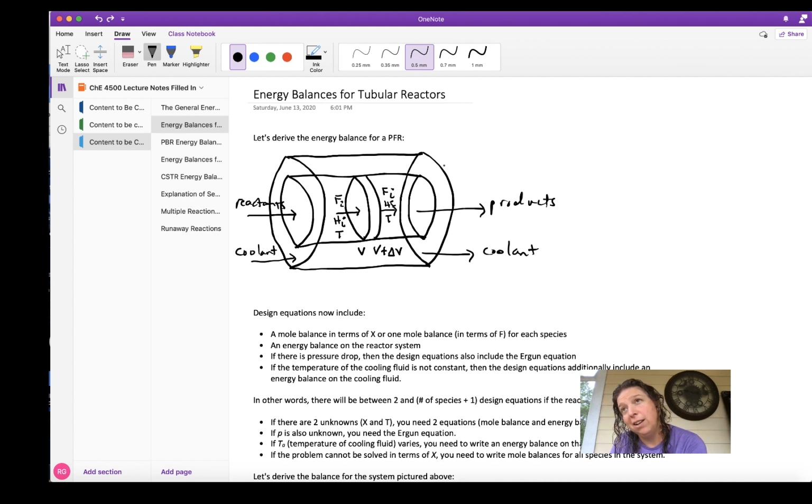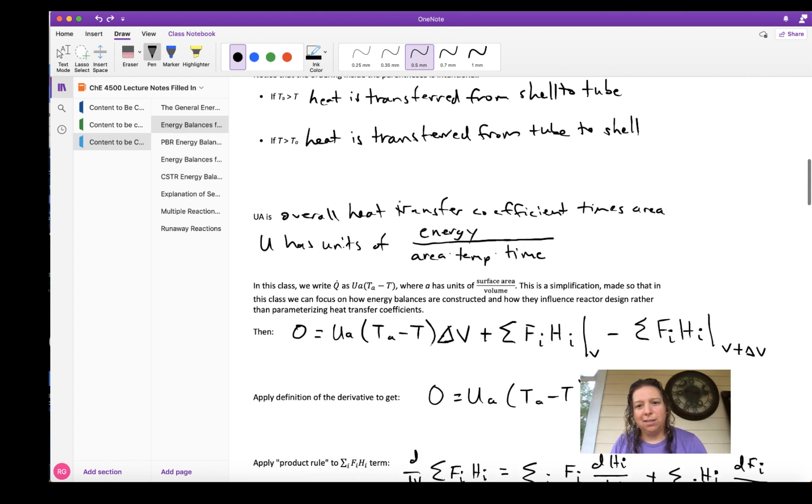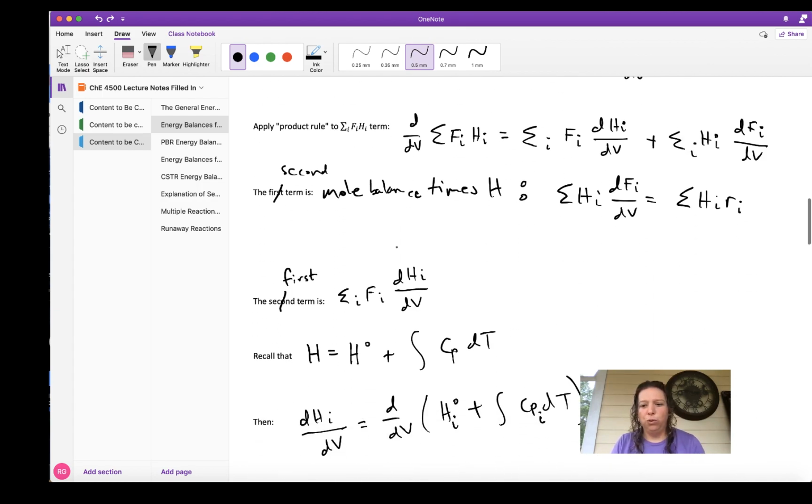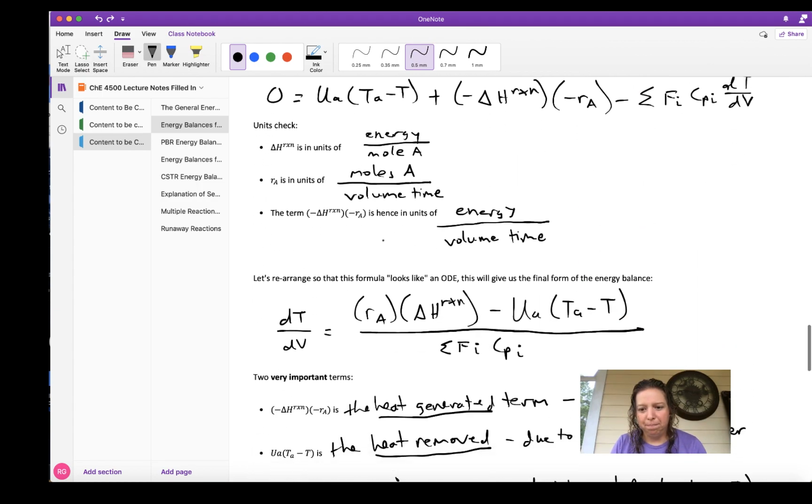So this becomes a guess and check solution. I guess an initial condition, which means I'm guessing a temperature at V equals 0, and then I see if the final temperature, which for the countercurrent heat exchanger is actually the inlet temperature, equals the specified temperature. That's a lot to take in. We'll do an example next that hopefully illustrates it.